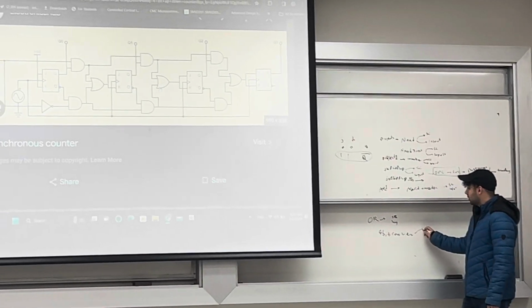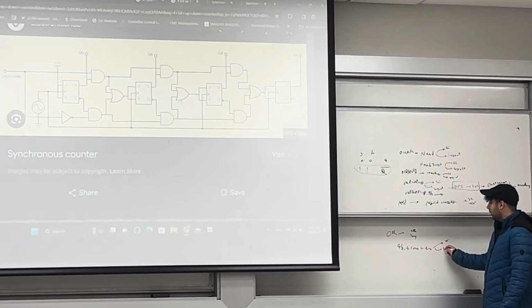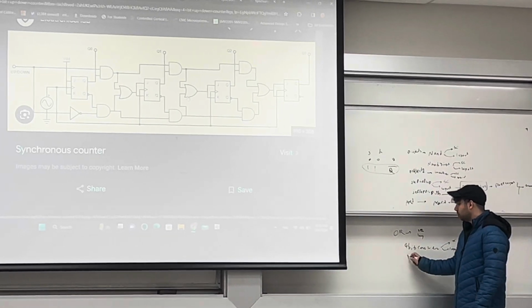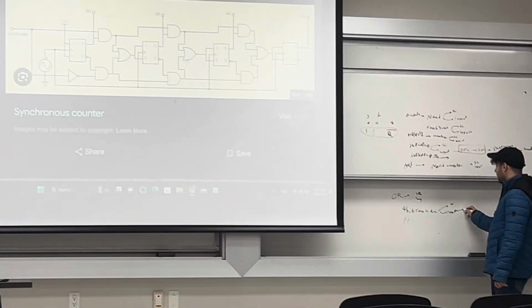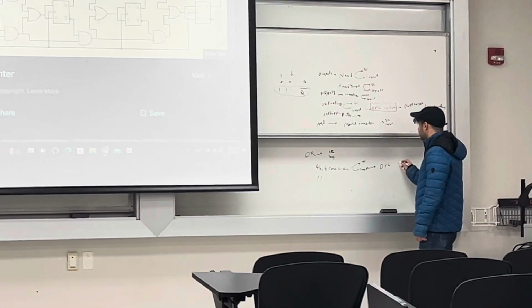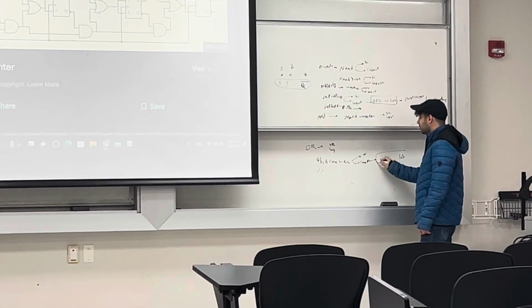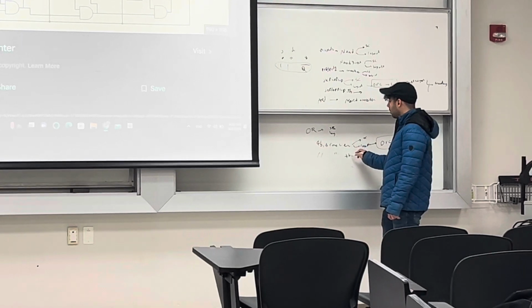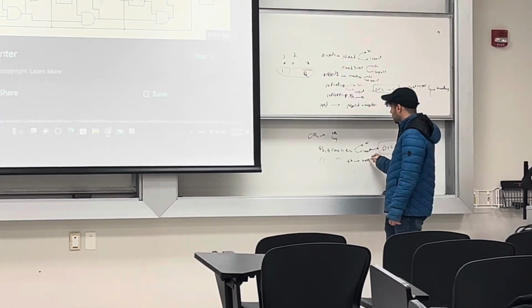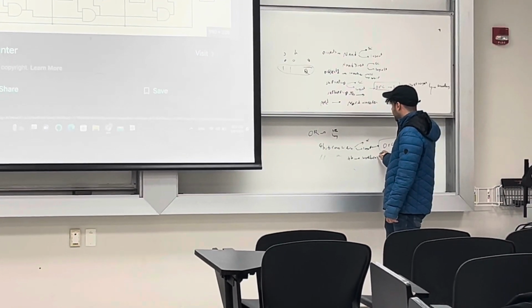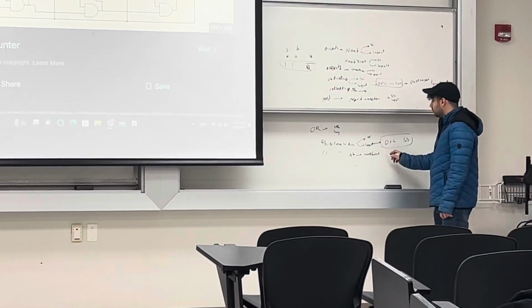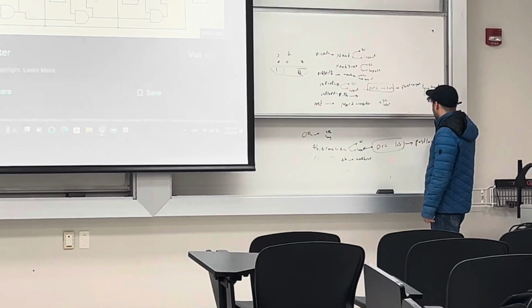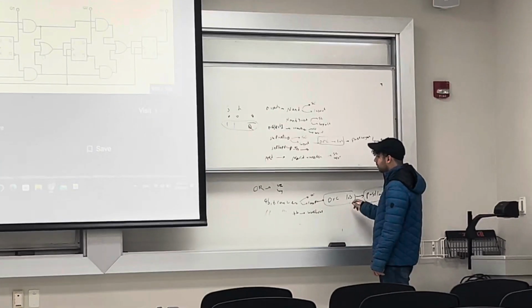For this circuit, design the schematic, design the layout, and then on the layout run DRC and LVS and take a screenshot of these two. Then make a 4-bit counter test bench, run the circuit and show the waveforms, and then do the post layout again for this circuit and show the output of the parasitic circuits.